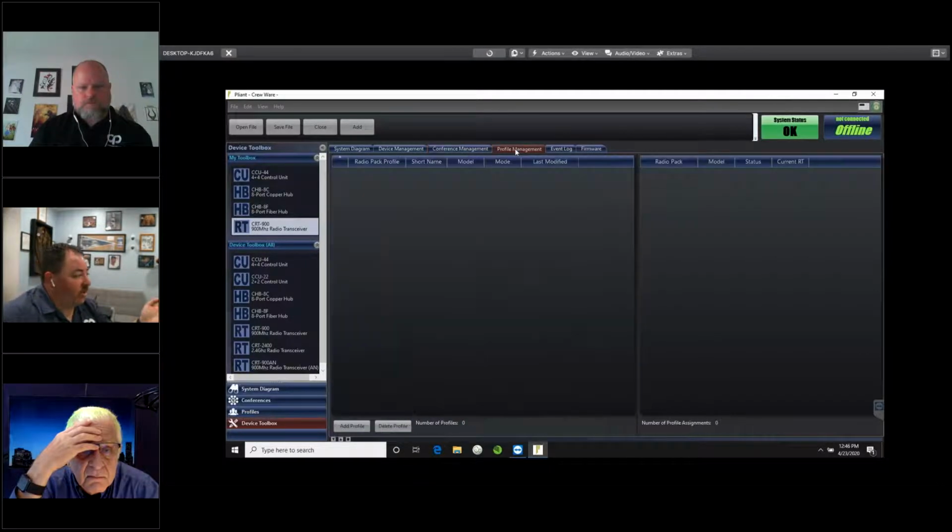The next step would be what they call a profile, or in other manufacturers' terms, this would be called a role. You can do one role for everybody, so everybody gets the same 4 channels, but you still have individual belt pack control of volumes and stuff like that for these particular people. But if somebody wanted a change in one channel, it would be a global change for all. Or what I like to do is create a profile, or a role, for everybody. Can you create one and then clone it over and over again for 10 people? Yep.